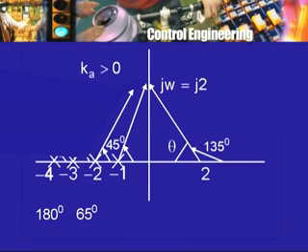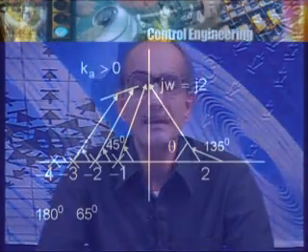Alright. Then I have the second pole, which is at -3. Here is the vector going from this pole to this point J2. Now what is the corresponding angle here? The height is 2 and the base is 3. So it will be tan inverse of 2 by 3. Now what is tan inverse of 2 by 3? Well, once again you will have to use your calculator, but let me say for the moment that it is something like 25 degrees.